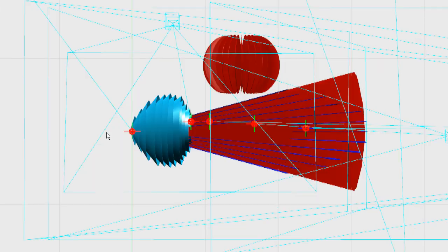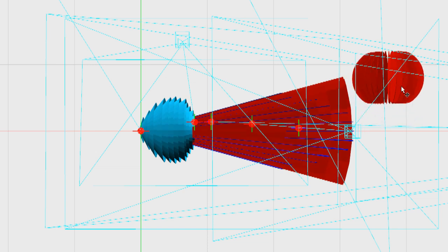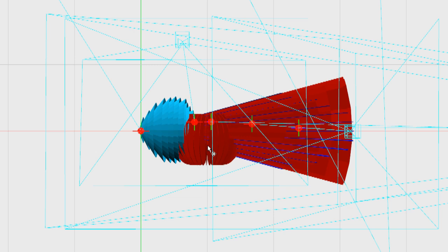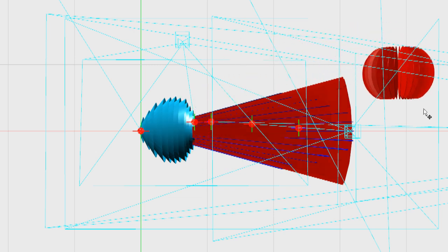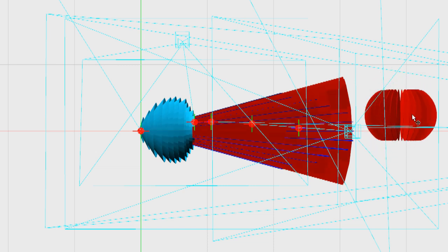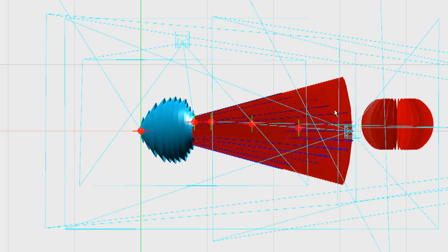I'm just going to flick back to the front view. So, for example, I've got a diversity receiver, and I also have an oracle connected to a single receiver. The single receiver would have the circularly polarized 8 dB patch antenna, and the diversity receiver would have the two Yagis with linear polarization diversity, and then both of those systems connected together via an oracle, which will look at the best picture and select between the two.